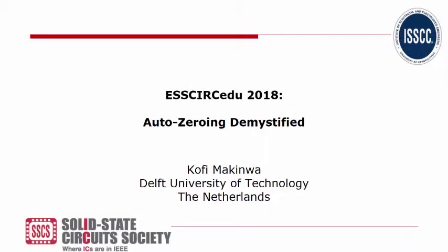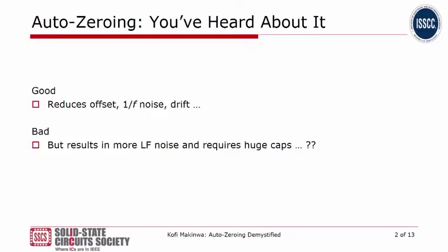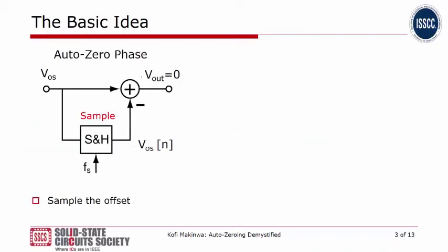I'm a professor at Delft University of Technology, and today I'm going to at least attempt to demystify auto-zeroing. You've probably heard a lot of things about auto-zeroing because it's a widely used technique. You've heard some good things, that it reduces offset, low frequency noise and drift, but you probably have heard some bad things about it as well. That is that it increases your low frequency noise floor and requires huge caps. So the object of this talk is to introduce you to the basics of auto-zeroing so that you can make up your own mind. So here's the basic idea.